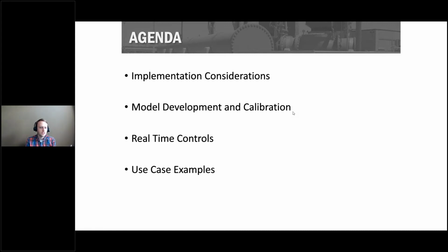There's a lot of documentation out there about how to go about doing that, so I won't spend a ton of time on it, just touching on some of the highlights and key things to consider. And then we'll get into real-time controls. Most of the time, these treatment plants, or other things you might use ICM for to help with design, have real specific controls to those facilities or processes. So real-time controls must be developed to mimic that if you're going to do extended period runs.